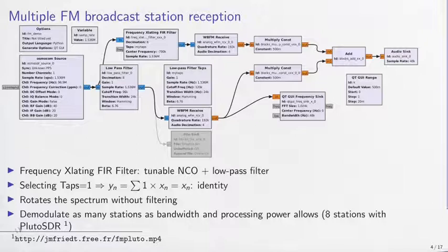In this example, we will consider the frequency band of the broadcast FM centered on 96.9, and because multiple stations are located adjacent to the center frequency with this 1.5 megasample per second and the typical spacing of FM stations of 400 kilohertz, we might expect 3 or 4 broadcast stations within the sampling frequency.